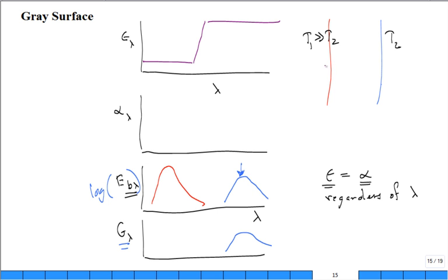Is it going to be throwing out as many photons as if it had been flat all the way across? The emission is going to be lower at that hot surface because it's trying to emit short wavelengths, and it has a low emissivity, doesn't it? All right. And then the incoming will be based on the surface 2 temperature, and it will be gobbling them up. It'll be absorbing them.